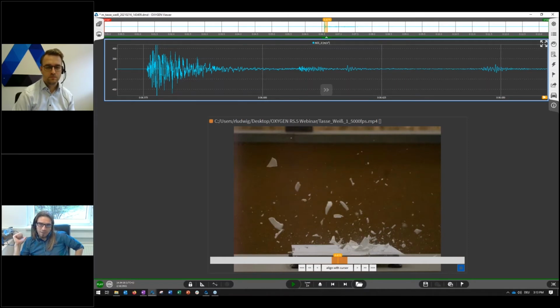Additionally, you can now connect several cameras to different Ethernet ports of your system. In the past, there was a limitation when you used several cameras in parallel for one measurement. All of them had to be connected to one and the same Ethernet port on your system via a switch. This is now obsolete. You can connect two cameras to two different Ethernet ports if you have them available on your system.